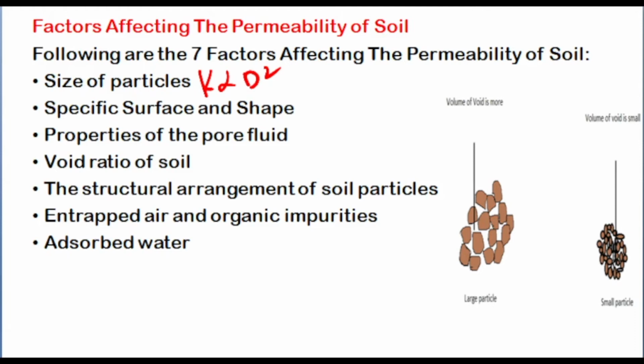Then we have something which is called the properties of the pore fluid. Properties of the pore fluid is nothing but the water properties, which is unit weight, viscosity, etc. Unit weight will not affect much, but when it comes to the viscosity, as the viscosity increases, permeability decreases.